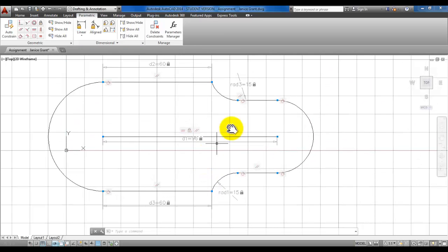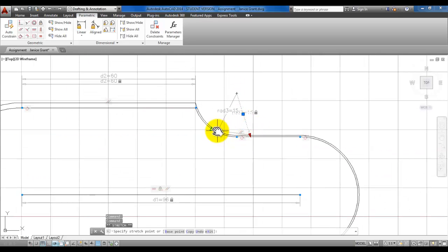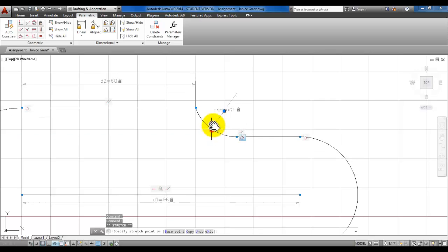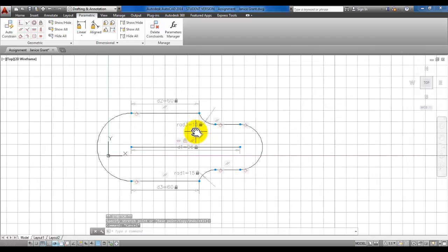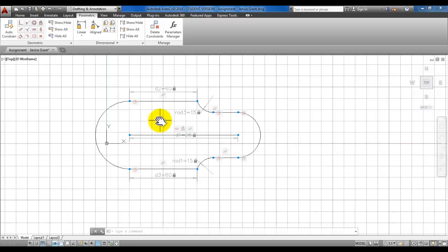And the book is asking us, well, this one's also a little bit off. I could actually just bring this around using grips, because this one doesn't show the extra lines. So we need to reestablish another radius over here. Constraint, we can select radius constraint, select here this arc, and then pick here. I clicked in space after selecting the location of that parameter.